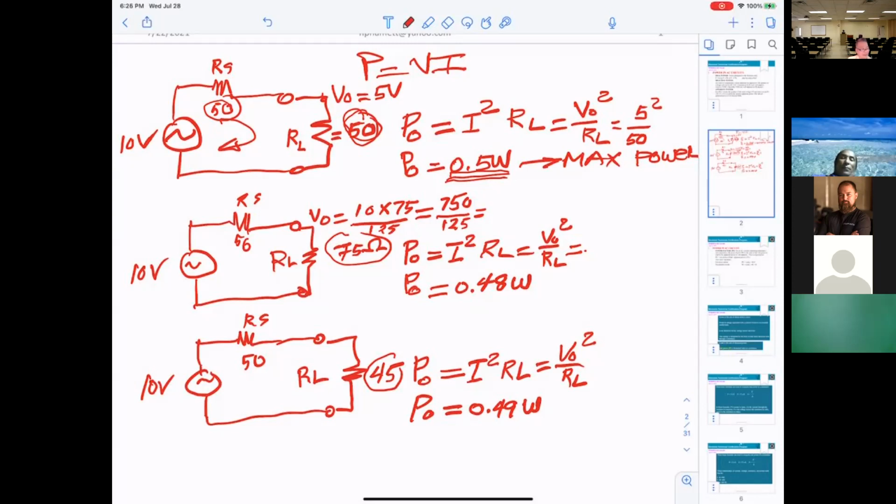But why do we get that? The reason is, with the CB, the output impedance can be either low or high, and the CC, same thing, the output impedance can be either low or high. So that's why when they design the circuitry, if they want the load at a low impedance, they don't use the CE amplifier. They have to use either CB or CC. That's regarding matching impedance.